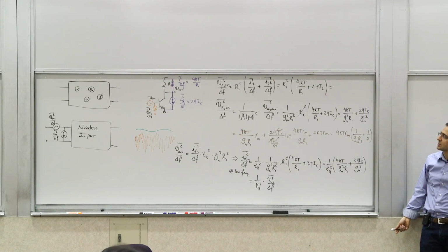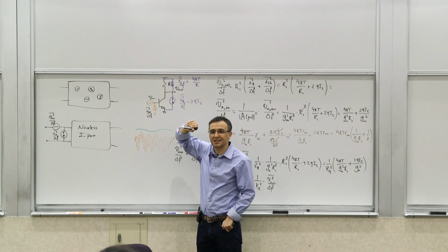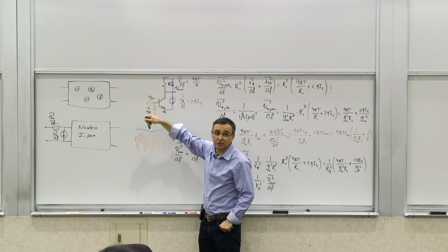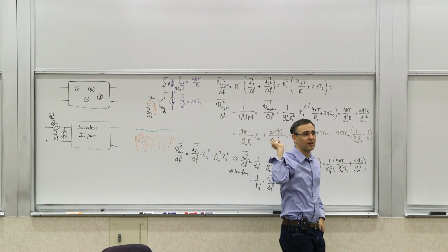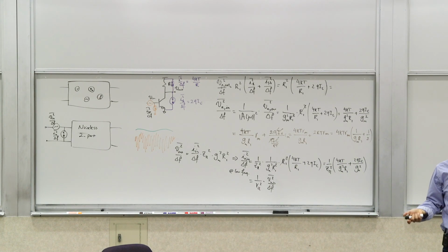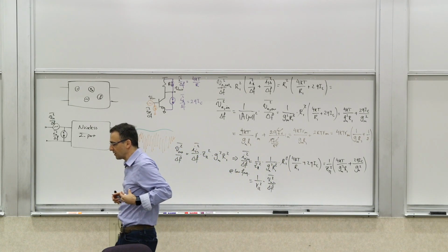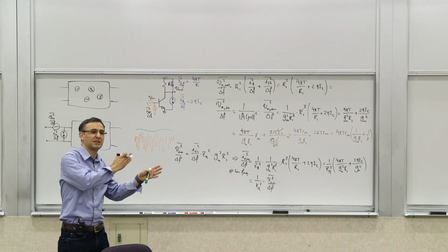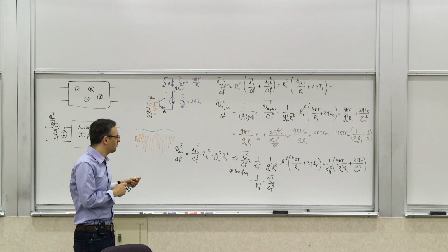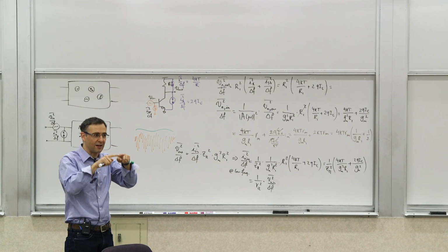The same exact source. It's the random thermal movement of electrons here in the resistor, as well as the random passage time of the electrons through the collector-base junction that determine the induced noise in both cases. So when, for example, a whole group of electrons that are packed together just cross the base-collector junction, there would be a spike in both current and voltage, right? So they would go up and down together.